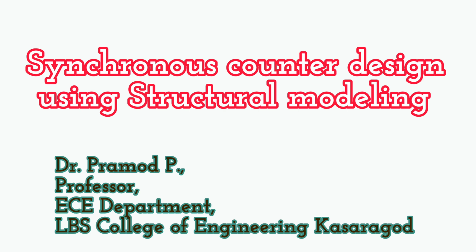Today we will discuss a very interesting topic, and that is synchronous counter design using structural modeling. In Verilog we can have different modeling styles, and in that we will be using structural modeling for designing a 3-bit synchronous up counter.